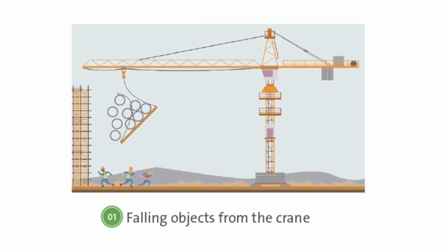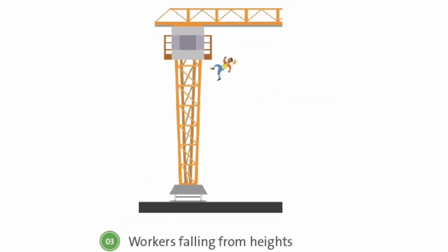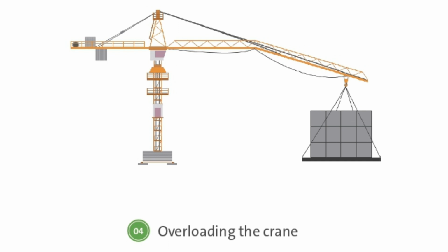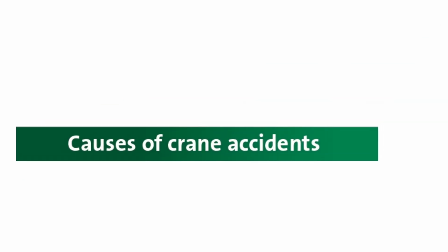1. Falling objects from the crane. 2. Collapse, overturning or catastrophic failure of the crane and or its lifting accessories. 3. Workers falling from heights. 4. Overloading the crane. 5. Collision with another crane and or structures nearby.